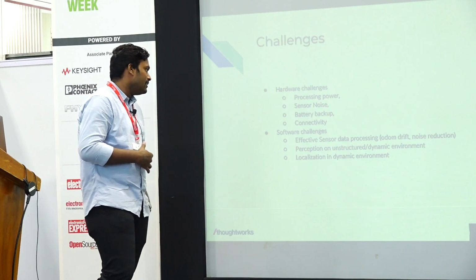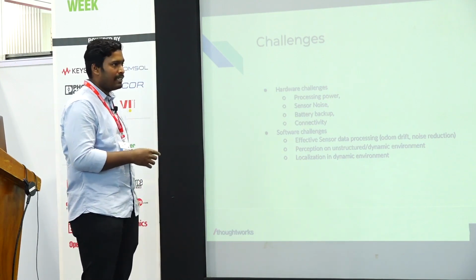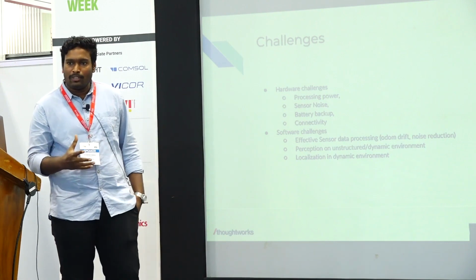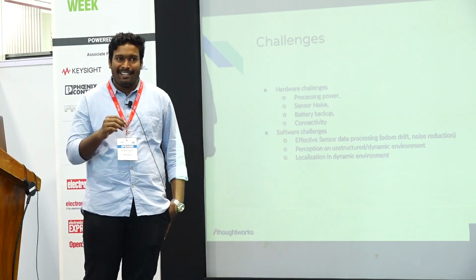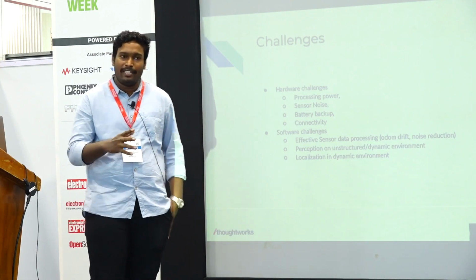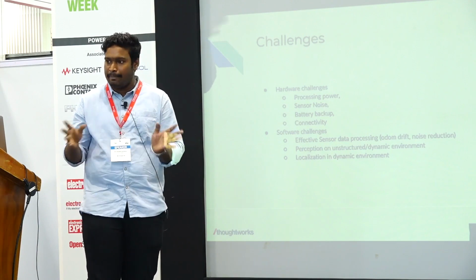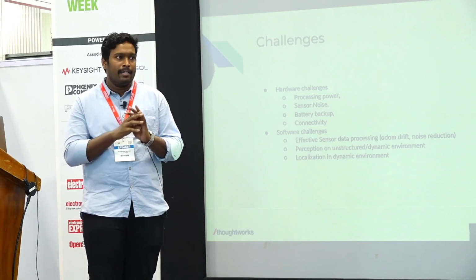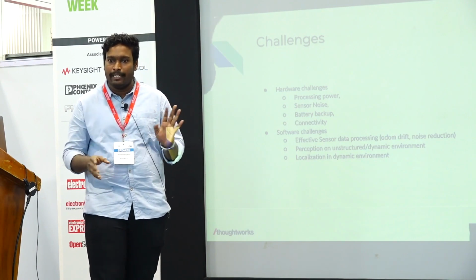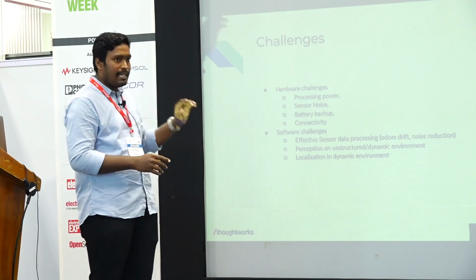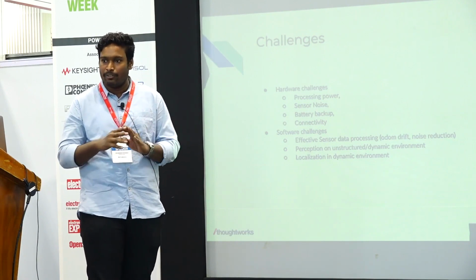And the software challenges, yeah, of course, sensor data processing. Your algorithm has to be very efficient first of all, because you are dealing with a bunch of data. It is not simple data. When you talk about 3D lidars and depth cameras, it is huge data, and at 120 to 130 frames per second, your algorithm has to be very efficient and reliable, because it should never fail.